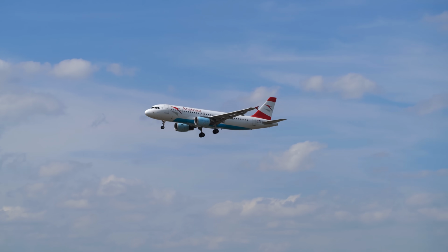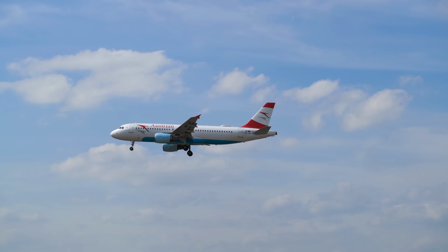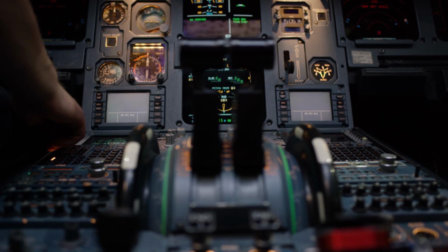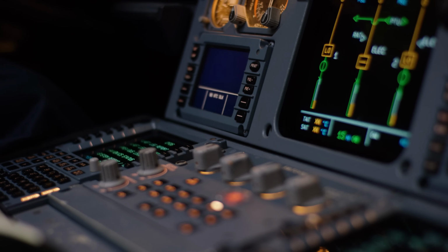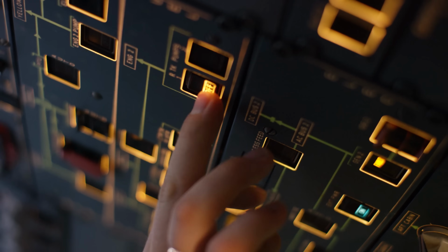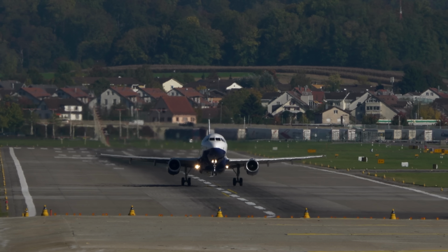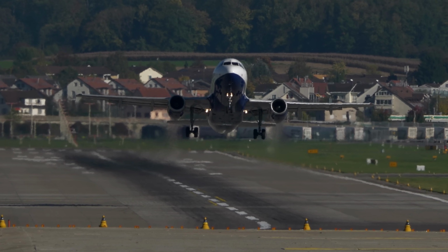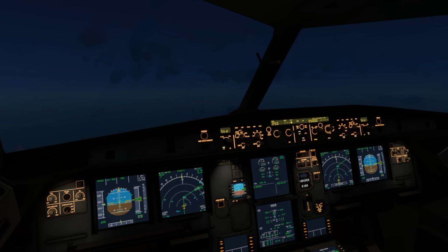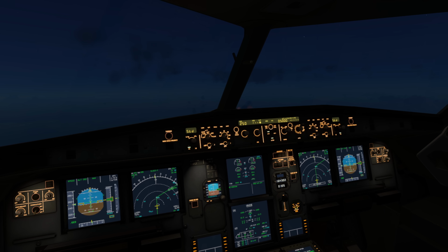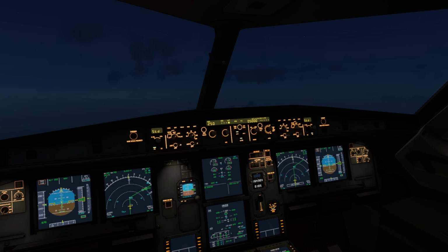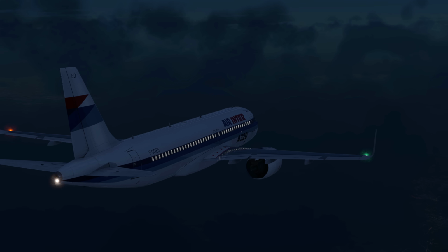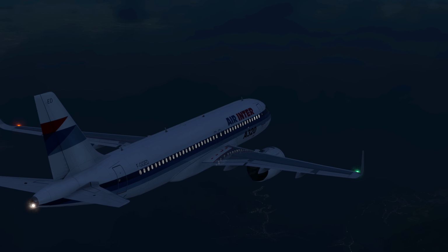Now, we need to talk just a little bit about the A320 and its fly-by-wire nature for just a moment. In a simple sense, fly-by-wire means that flight control inputs, either made by the pilot or the autopilot, are fed electronically to a series of computers on the aircraft, which then activate the hydraulic systems that move the ailerons, elevators, rudder, and so on. Because of this computerized nature, Airbus was able to install a number of protection systems, and the fly-by-wire operates the plane within a safe boundary. This is supposed to prevent the plane from entering excessive descents, for example, in normal flight.